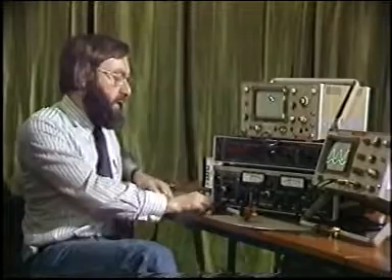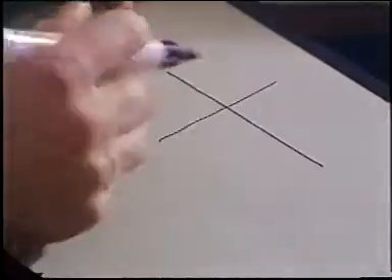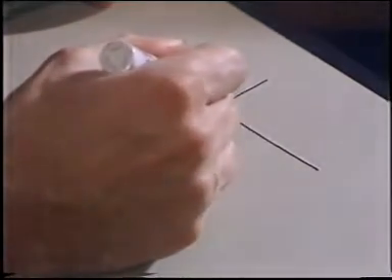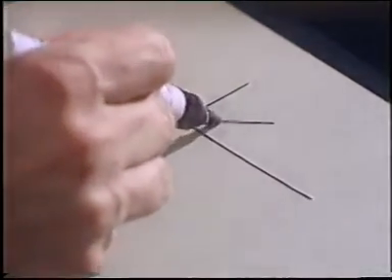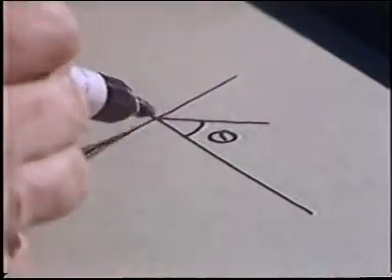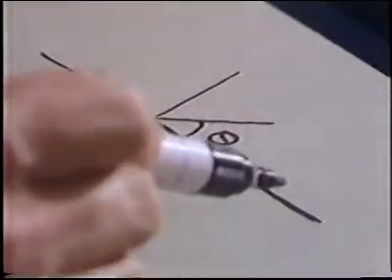Now, this leads to the idea that sine wave signals can be represented in the form of a diagram, a phasor diagram. The signals are plotted on a diagram of this sort in the form of a line with length proportional to signal amplitude at an angle, the phase angle, measured relative to the phase reference axis, the horizontal axis here.